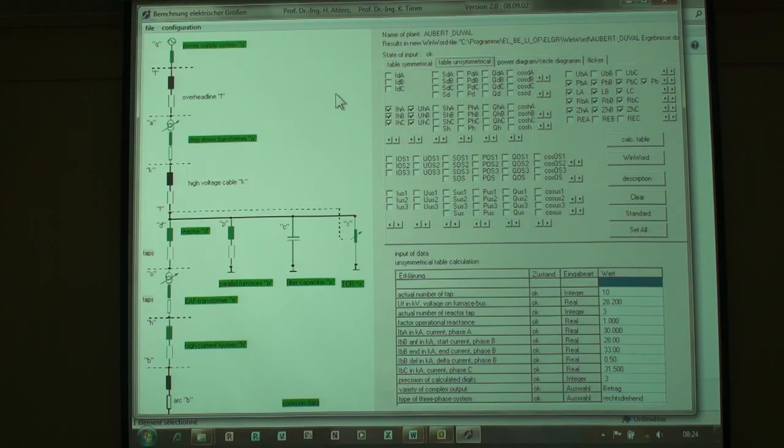Afterward, knowing this, you know the maximum tap, and you have to decide the lowest tap, the lower stop and the maximum. For a furnace of 150 tons, it would be stupid to have a lower stop at 150 volts.